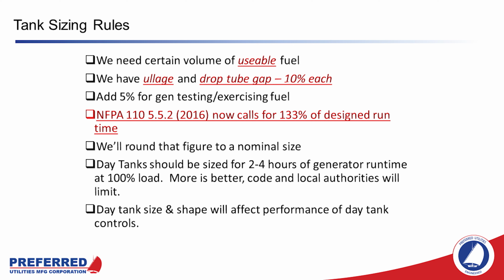So many jurisdictions have rules about how much fuel you have to have on hand. In Texas, hospitals are required to have 24 hours worth of fuel on the facility. Florida just passed a law a couple of years ago saying that you have to have enough generator capacity to air condition your living space, and you need to have 120 hours of fuel on the property. This is applicable to nursing homes and assisted living facilities.